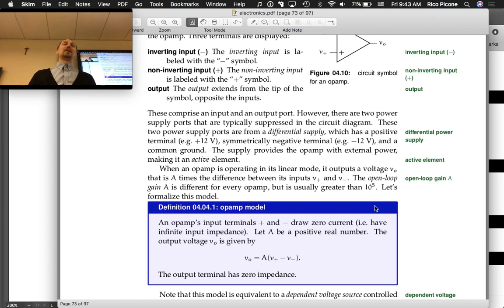So I talked about how if you put a sine wave into a nonlinear system, you probably aren't going to get a sine wave back out, right? So in your 315 class, you guys have talked about Fourier series a little bit, yeah? The idea being that any periodic signal is composed of a bunch of sinusoids. You can approximate it by just being a sum of sinusoidal terms.